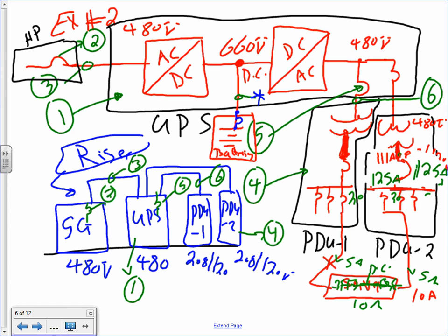Did we look at a data center? I don't think we have seen one yet. We're going to be at Allianz, guys. When we go to Allianz, you're going to see a room full of batteries that's feeding a UPS system. So here's what happens. The power comes from the switchgear into the UPS. The UPS converts it into DC and ties it to a battery system.